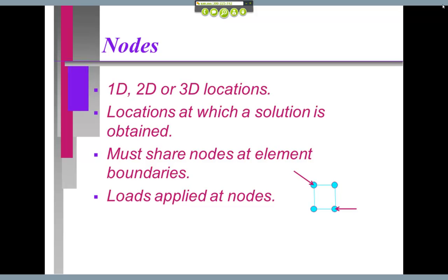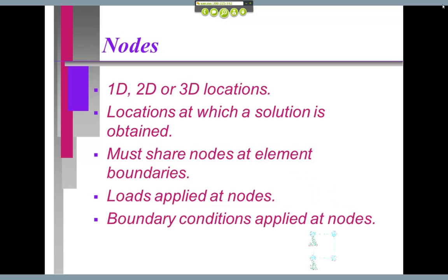Element, what I'm really trying to tell it to do is distribute that force on two nodes, or on however many nodes are lit on that particular edge. And so there are some calculations going on behind the scenes that change that. But the solver expects the loads to be on the nodes themselves. And nodes are where the boundary conditions are also applied.